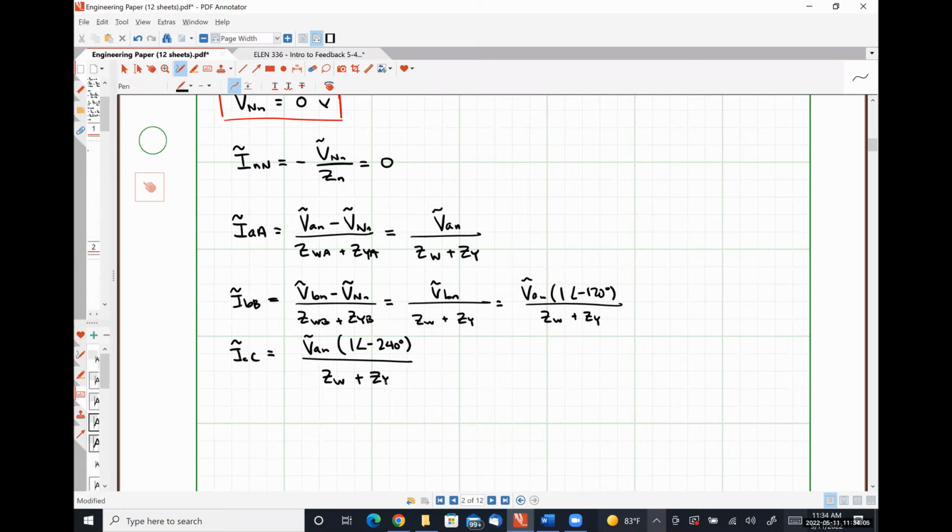Right. So what happens whenever one line fails within the balanced system? It becomes wildly unbalanced. In your power lab in your senior year, we used to investigate that exact thing. If you have a 3-phase motor and you just disconnect one of the phases from the power supply, the motor will still run, but it's no longer a smooth and constant oscillation.